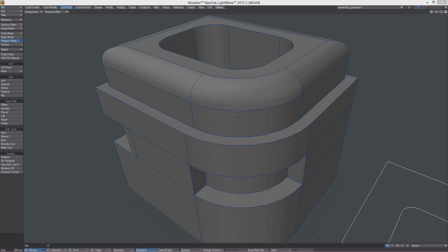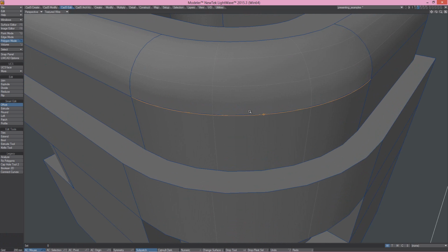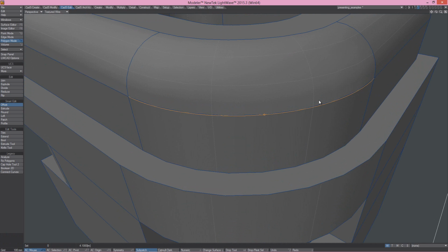And the most important property of smart mesh is that each shared edge between surfaces or polygons on a smart mesh has identical detail level on both sides. So this NURBS surface and this NURBS surface over this shared edge have identical level of detail.